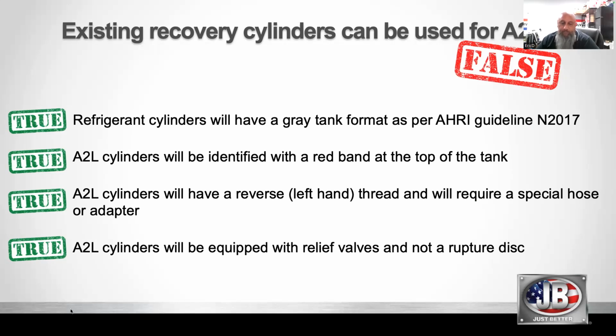You are going to require an adapter of some sort to take refrigerant out or get it back into that refrigerant tank, an adapter or a hose with a left-handed thread on the end of it. And you see that actually with some of the other flammable refrigerants on the market as well. So it's not new, but certainly new for most of the people out there in the field.